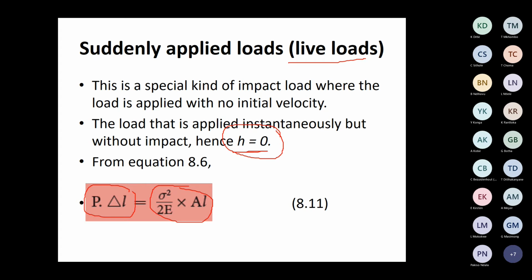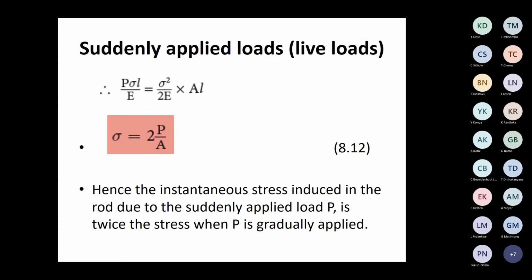All right. When you have done all the substitutions and calculations, you come out with your stress equal to 2 times P over A: 2 times the force divided by the area. And people, again, this A is my cross-section area. Right, that is important. My cross-section area.